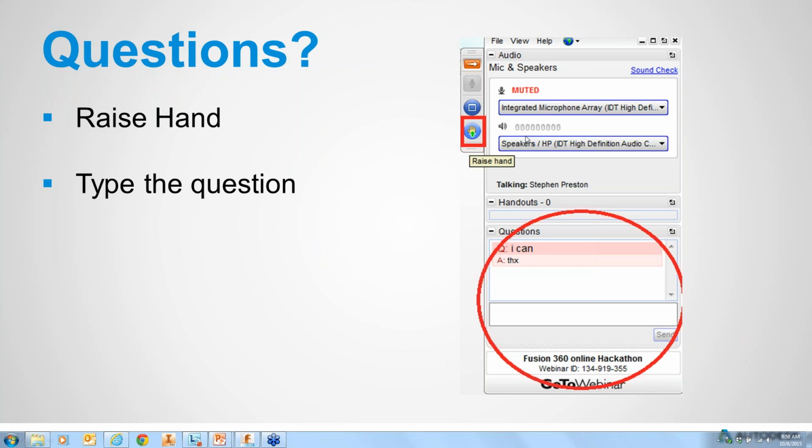So really the only reason you would choose one over the other is how you want to parametrically control it. If I want to edit it, maybe one's more convenient than the other. But as far as the API looking at the result, if I'm just looking at the BRep body by itself, there's no way for me to tell if it was created one way or the other. I'm just looking at the result. It could have been imported from a STEP file even. It's 6 planar faces.